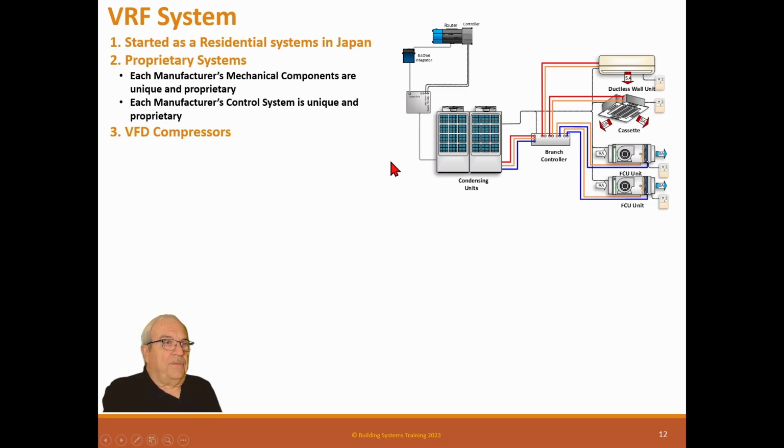This can. These have VFD compressors. It has VFD supply fans on the evaporators, and it has VFD fans on the condenser fans. It has poor heating performance, unfortunately. Like a mini split, this has a very high cooling efficiency ratio. You can get them up to 24 SEER in cooling, but in heating, they're just a heat pump. So they have problems when it starts getting below 32 degrees Fahrenheit. They'll go down to maybe 20 degrees, but their efficiency is really poor at that level.